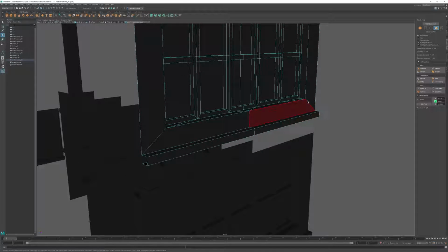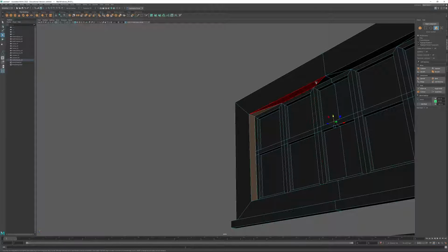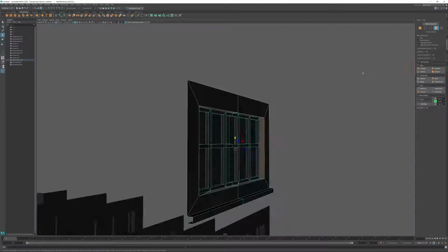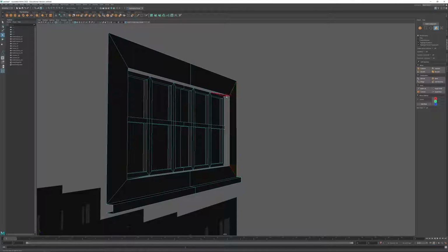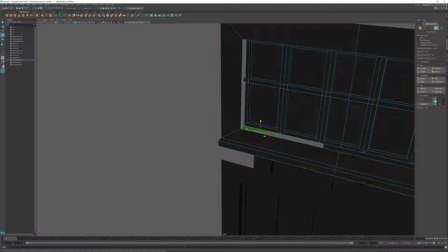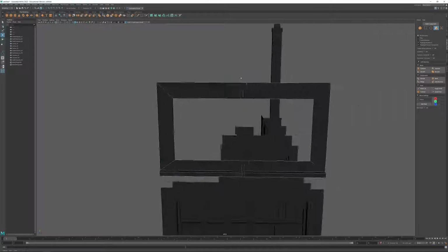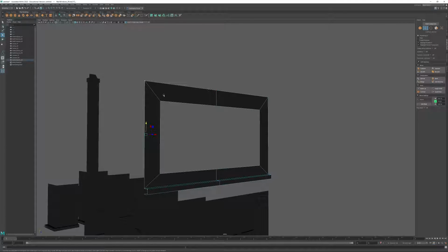And so, again, I can go and grab all of these shapes here, all of these faces that are contributing to the width of the windows. Like that, and delete them. Followed by, missed something, there it is. Followed by deleting the windows. And then we can go and just take all of these vertices here and target weld them.